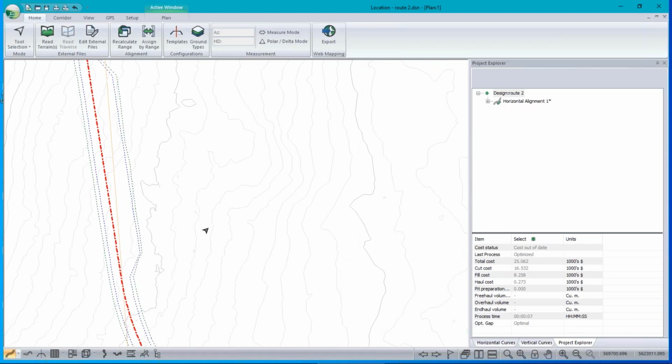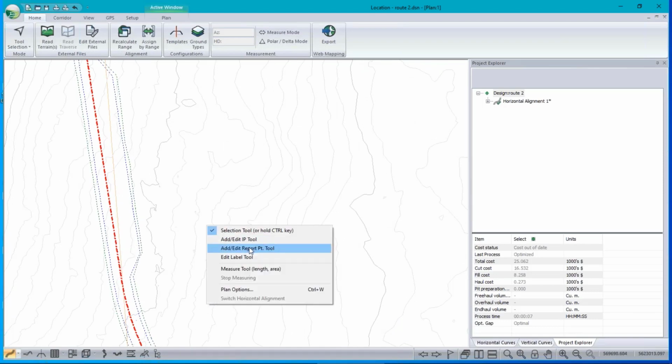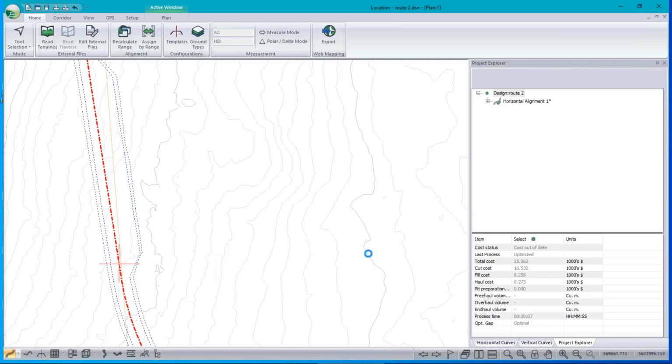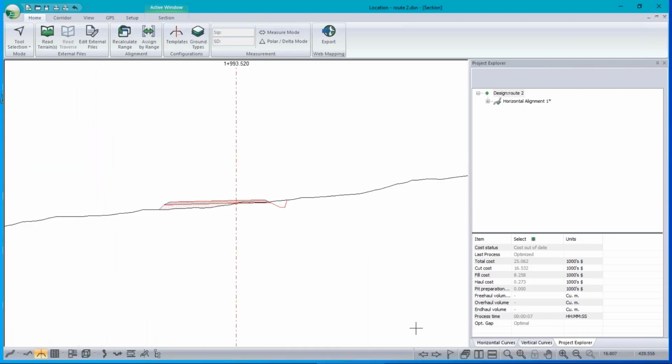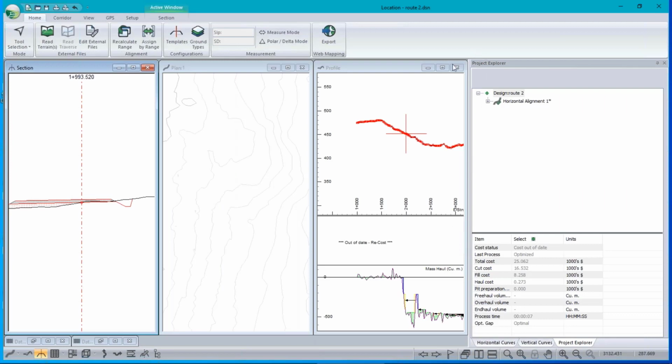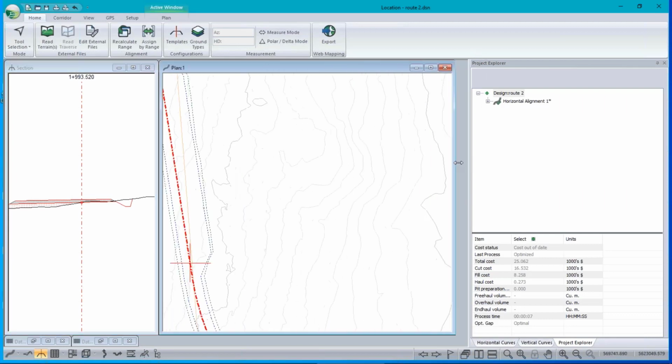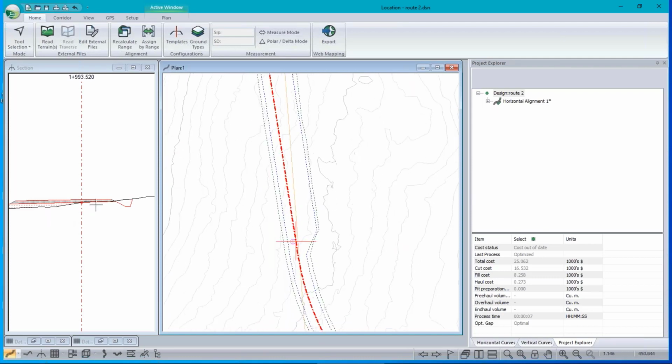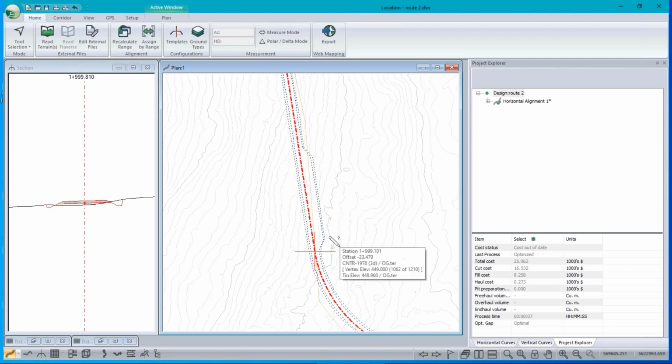So if I look at a cross section right in the middle here, right there, it'll be tapered out halfway. And I don't need the profile. There's the plan. And there's halfway tapered. If we go back, there's the full turnout. There's tapering, tapering, and back to the narrow width. So I didn't need to make a new template. I could just override the parameter.